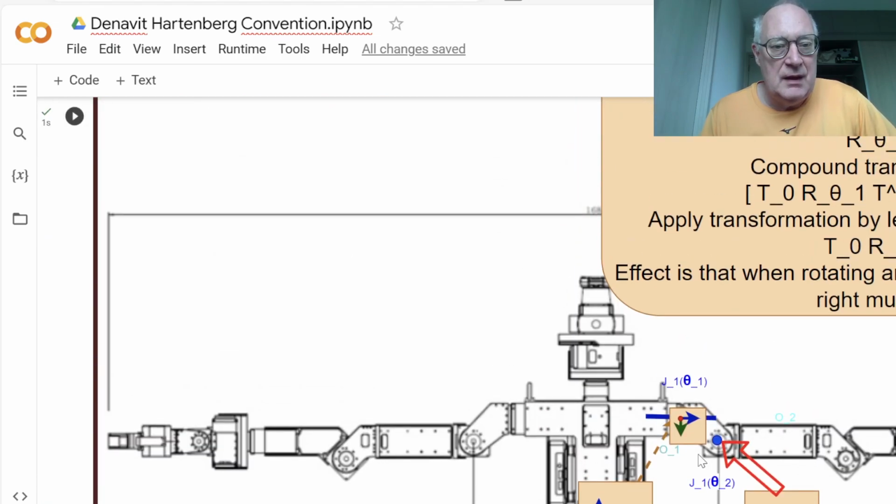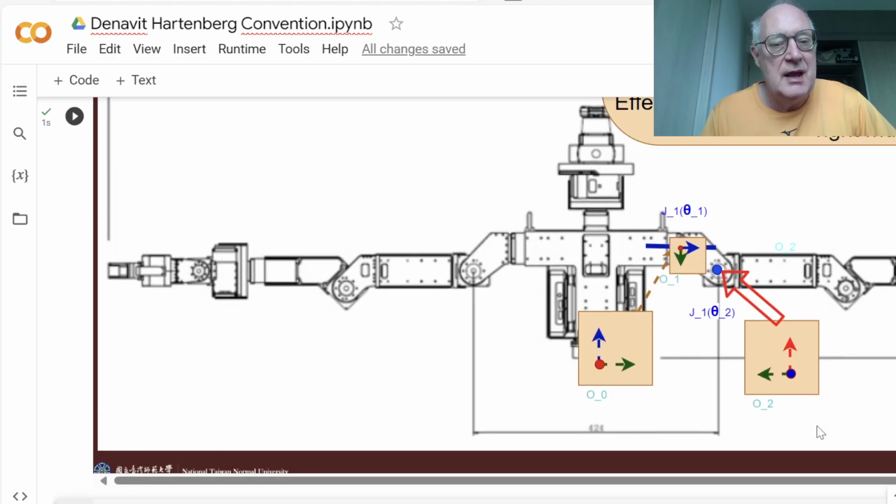So here, this is actually what we have done previously as well. The previous z-axis is going upwards, the x-axis is going out of the page, so the previous z-axis and the next x-axis are perpendicular to each other. Similarly here, the previous z is going out this way and x is going up, so this is also a 90-degree angle.